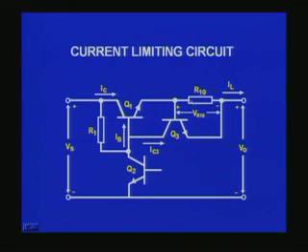But when I draw a large load current which makes the voltage drop across R10 nearly 0.7 or a little more than that, this will make the base of this transistor larger in voltage than the emitter by this voltage across R10, and if it is 0.7, for example in the case of silicon, this Q3 will be switched on. When it is switched on, the current will start flowing through this, it will avoid this Q1 transistor, and therefore the output will be almost reduced to 0.